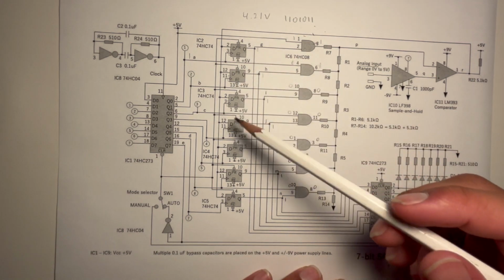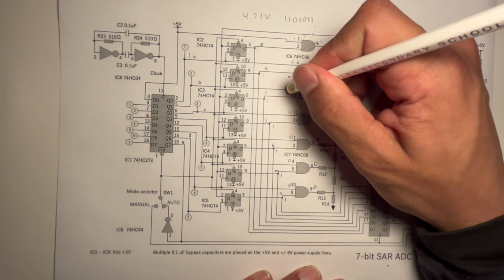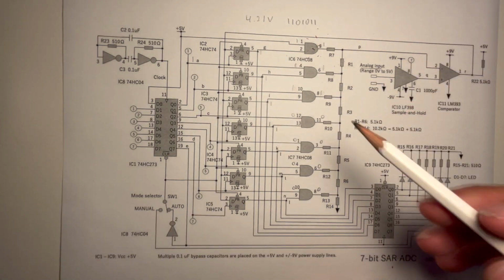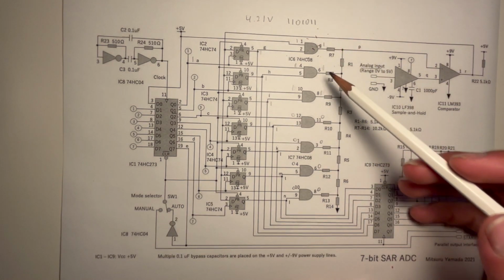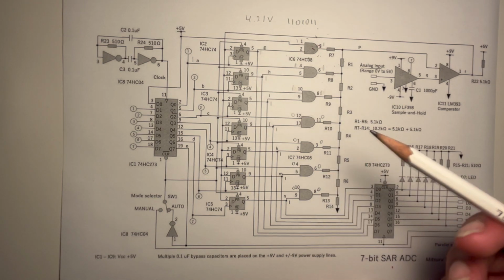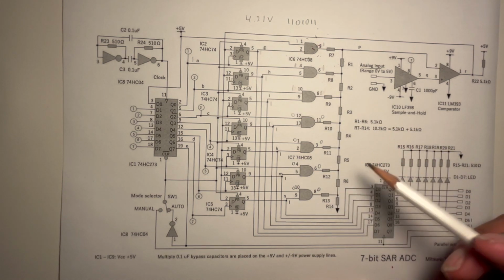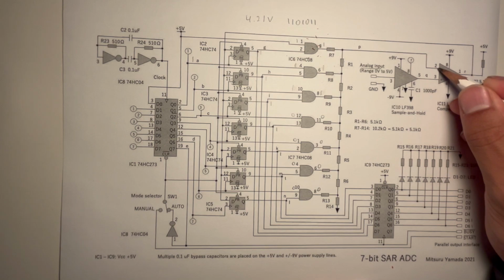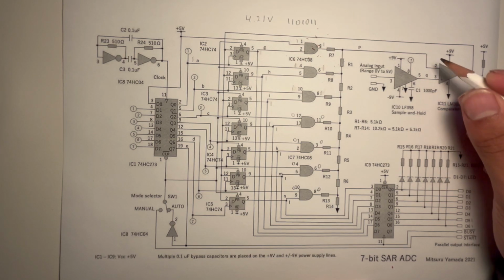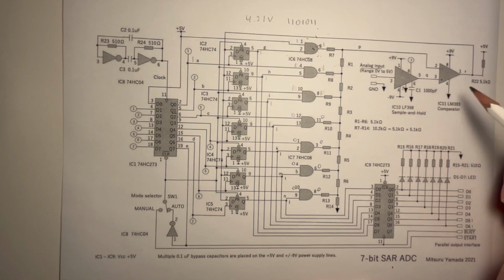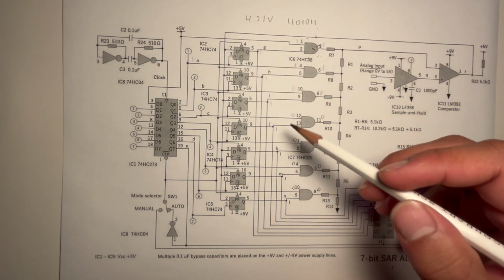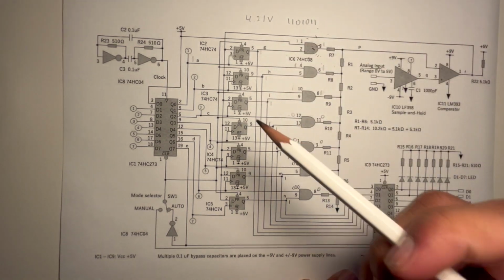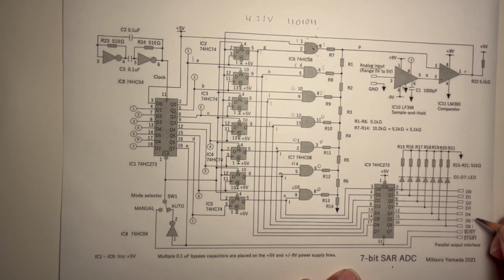Next, this process repeats on the next pin, which again bumps this to a 1, bumping this to a 1. And so now it's going to compare it to the value 1, 1, 1, and then 4 zeros. So this voltage that's outputted is 4.41 volts. So now we have 4.41 volts as the reference voltage and 4.21 volts as the voltage being tested. So 4.21 volts is now less than 4.41 volts, which means the comparator is going to output a low, which is going to change the third output to a 0 and store a 0 in this D flip-flop. And so we can put a 0 on D4.